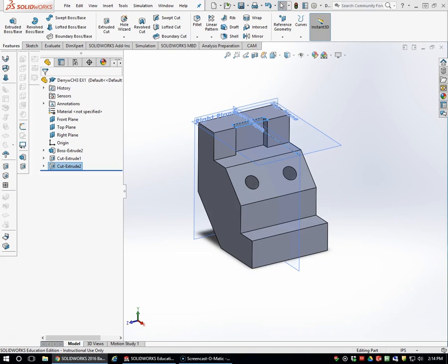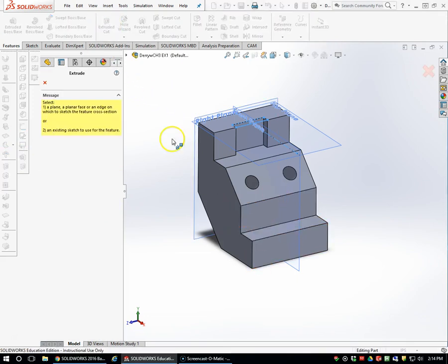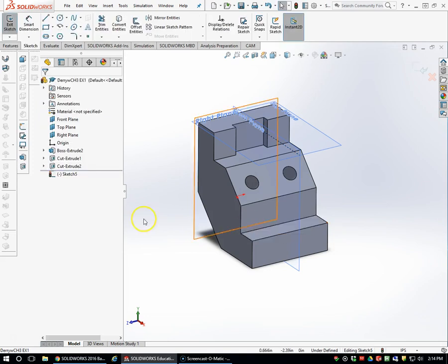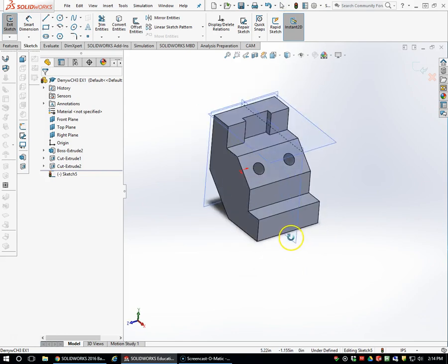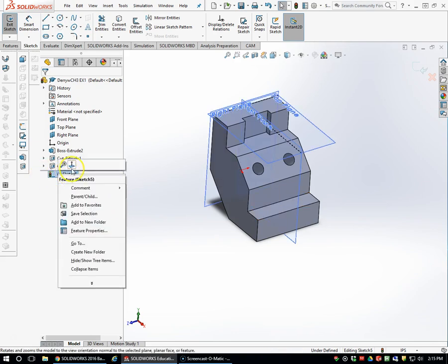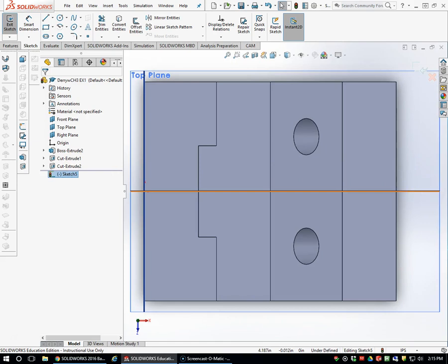to go in and add some relationships by putting a new sketch on this face. So instead of using the sketch command, we learned last time that if we just pick extruded cut and then select the surface, it's going to automatically activate the sketch command and allow us to save a couple of clicks. So right now I have a sketch on this surface, and I can look normal to that surface, which is a good habit.